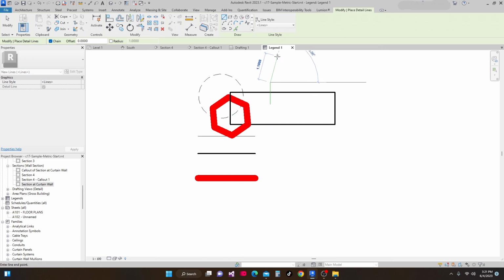And then if I wanted to change my plot style, you cannot change it because we are on chain. If you want to change your plot style, just hit escape once, and then again you go to this line style, and then go to this medium, and I can make a line again.